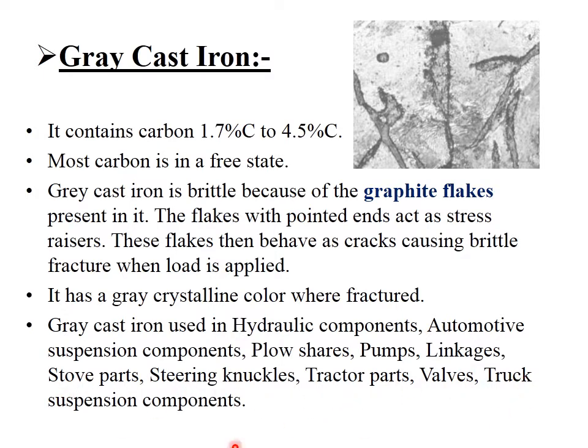Also in automotive industries, you can see agricultural vehicles like tractor parts, valves, and suspension components. Here you can see the suspension components, because of having good compression strength, they can absorb shocks quite easily. So this is gray cast iron.